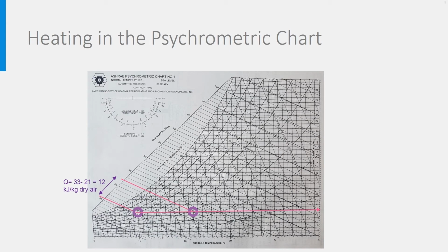If you want to estimate the sensible heat factor SHF on this chart, let's take again the example of air at 20 degrees and 5 gram per kilogram humidity. Here too, you need to draw a line between 0 and a point. You have then to draw a line parallel to this one, but starting in the middle of the small diagram above. Where this line crosses the circle, you can read the SHF, 0.6 in our case.